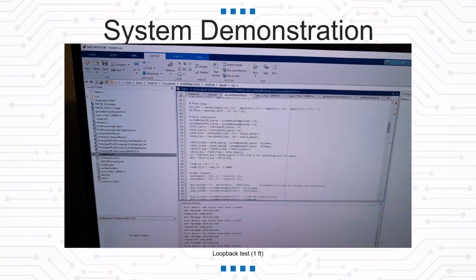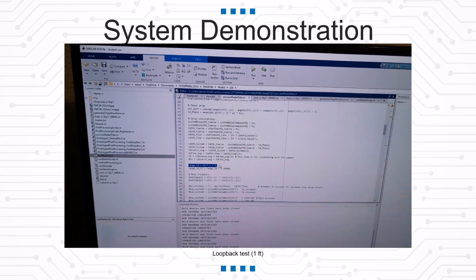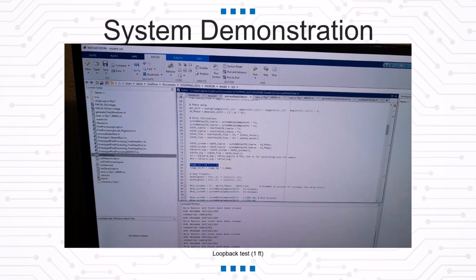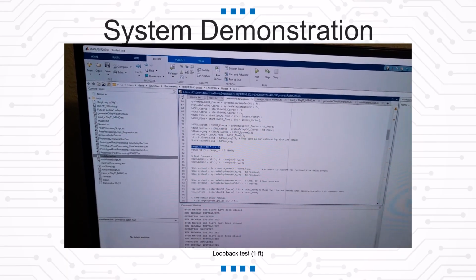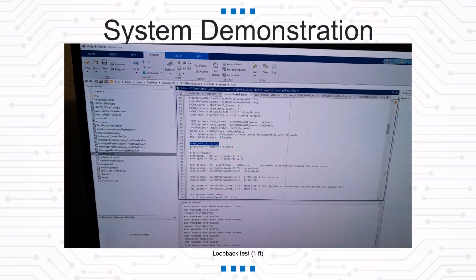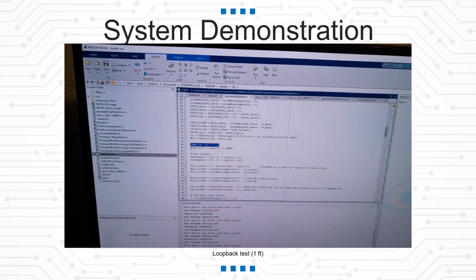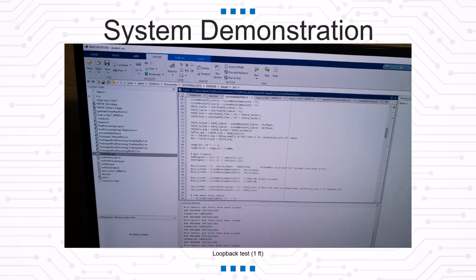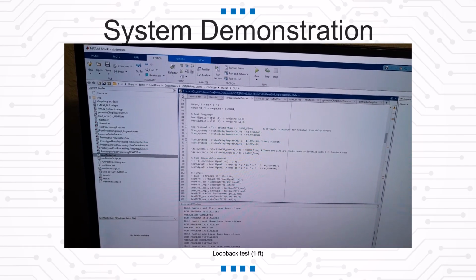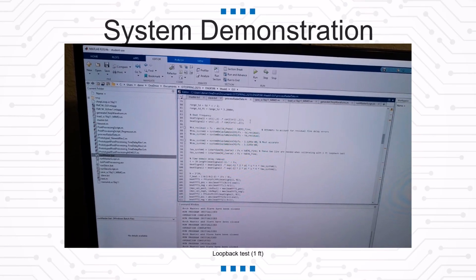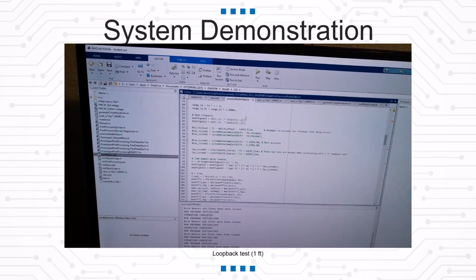And then we calculate the time delay in the time domain, and we calculate the range in the time domain. We use cross correlation to get the time delay. And then we mix the signals. We mix the transmit signal with the conjugate of the receive signal to get the beat frequency.